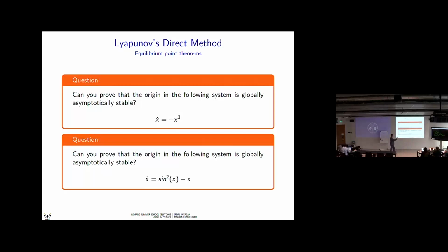And then for this function, let's not do it, but you can define it slightly differently. You have to define something related to sine and cosine, right? But the story is the same. Propose something positive definite, find V dot, substitute here, and then see. Let's say you choose a Lyapunov function, you substitute, and there is no result about the definiteness. What are you going to do? The function is something like 1 minus x squared.